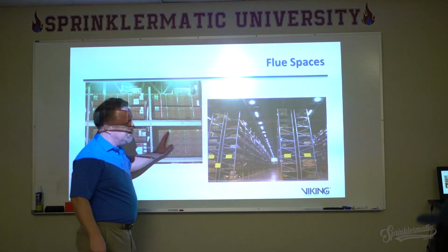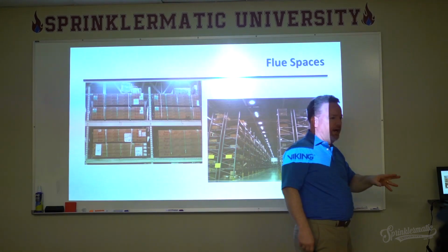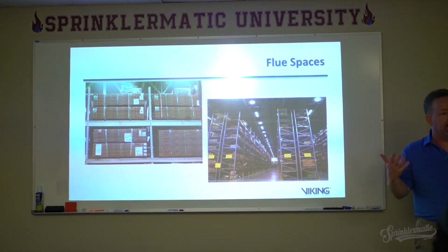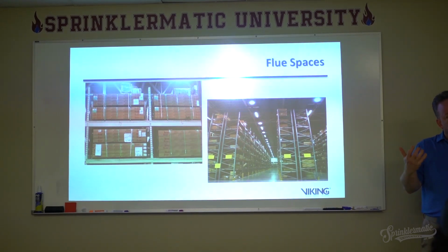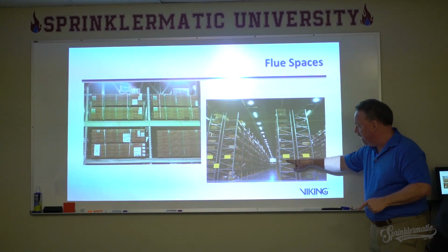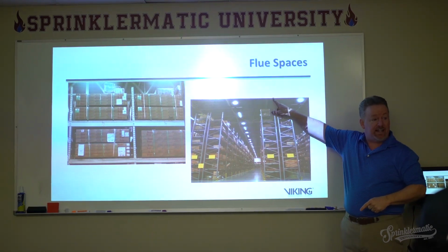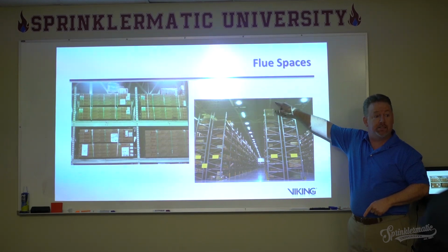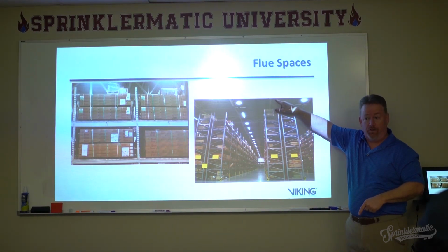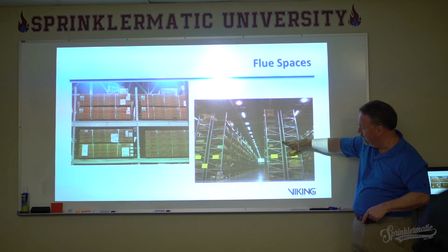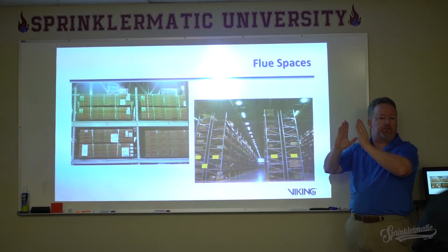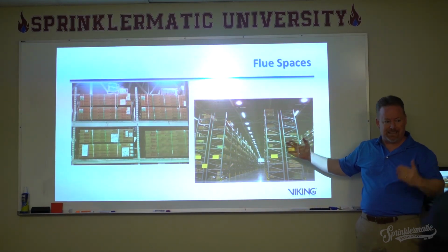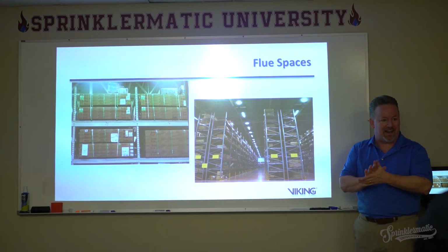And these are important. Flue spaces are important in rack storage for two reasons. Now remember, we said they entrain a lot of air in there, so it gets a fire going. But what it also allows to happen is, if I get a fire going in here, it allows that heat to go up through the structure. Where are my sprinklers? They may just be at the ceiling, or they may be somewhere in racks here. It allows that heat plume to travel up through. What does it also allow once the sprinkler operates? Water to come back down.